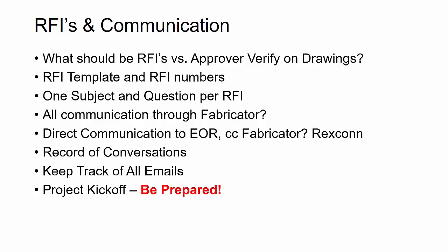the project, and you have a lot of the questions and even some of the RFIs that you're looking for the early milestones on the project ready to go and even to discuss during that kickoff. What you're hoping to do with the fabricator is go almost page by page in the design, or go item by item in the scope and make sure that you have everything clarified. And so you want to get some of these big questions that you're going to actually see in the slides in this part of the video, and you're going to see if you can get some of these clarified during that kickoff.